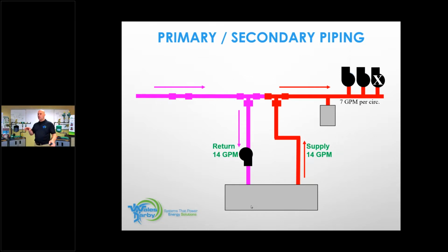So the majority of the boiler manufacturers, depending on the size of the boiler, will give you somewhere between 10 and 20 equivalent feet worth of pipe that can be attached. So including your elbows and your linear feet of pipe, they'll give you about 10 to 20 feet from the boiler connection point to the bowl of the T's going into your primary, secondary T's. So hopefully that'll answer that.